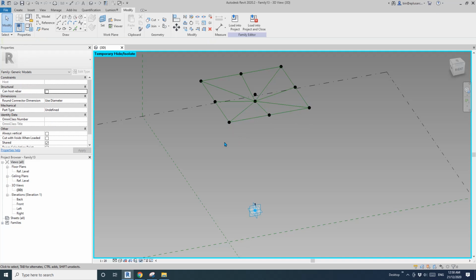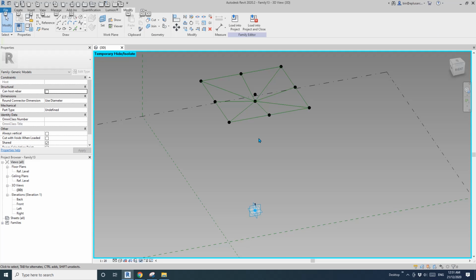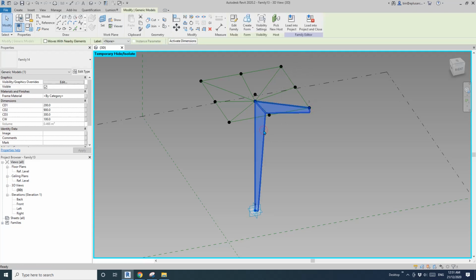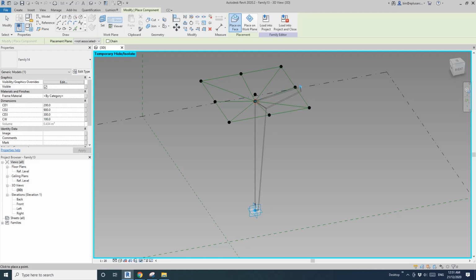Okay, so now let's do the rest. I'll try the Alt key. Alt, create, C, and family, FA. So 1, 2, 3. Temporary hide, HH, Alt CFA. 1, 2, 3. HH, Alt CFA. 1, 2, 3.